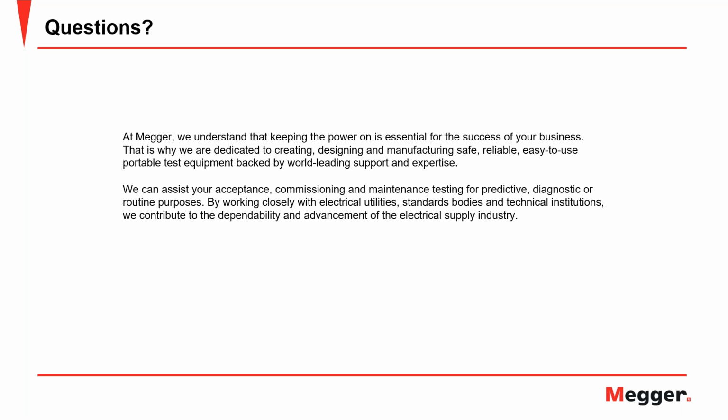If you want to test those breakers, you would need AC current. So yes, you can have a ductor with 100 amp capabilities, but that's not what we are looking at right now. You have two ways of performing the test. One is primary injection, the other is secondary injection. Primary injection, we talked about it a lot. It's the most recommended method, but yes, moving things around can be challenging.